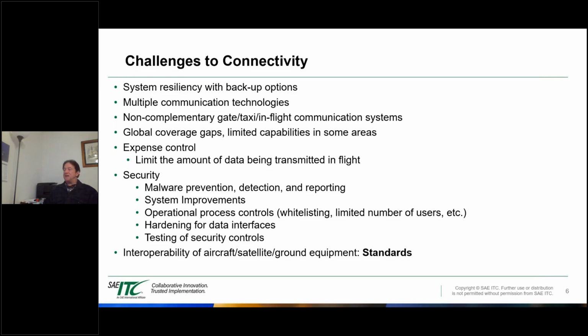You need to winnow that down to be looking for out of range and poorly trending situations. So you're not just transmitting bulk data, which really isn't a whole lot of usefulness to the airline, assuming that everything is in normal operating ranges. So clearly you want to just focus on those things which could be problematic.